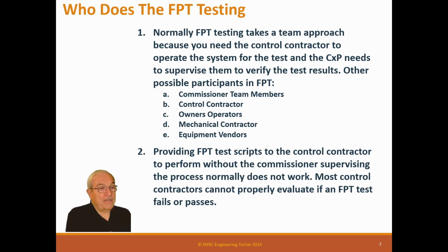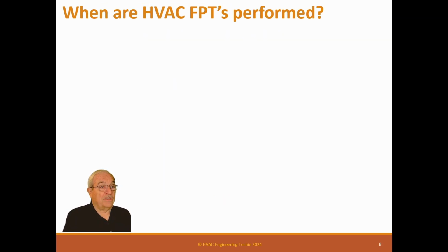So it's best for you to be there to watch them as they do them and say, well, okay, that one worked. Or, no, boy, that one didn't work. Something's really wrong. It's just much more productive to be there to supervise. Now, there are some instances, like long-term trends, where you're not going to supervise those, but you're going to get the results back. One thing about supervising a control contractor is you're training him what a good trend is or what a bad trend is, and then eventually he'll be able to figure it out for himself.